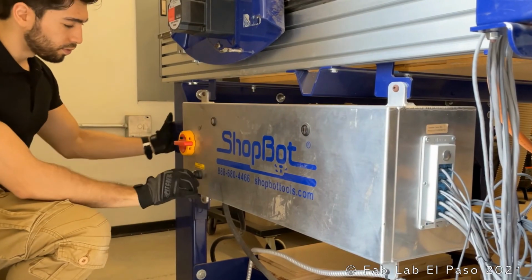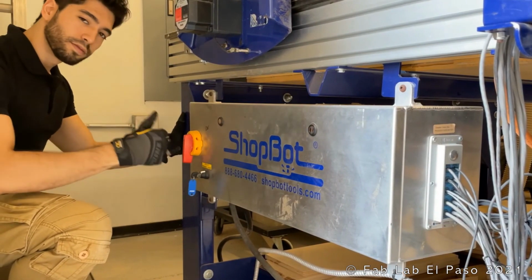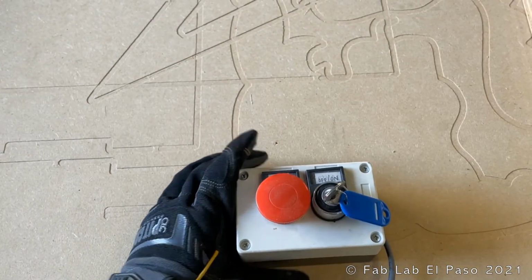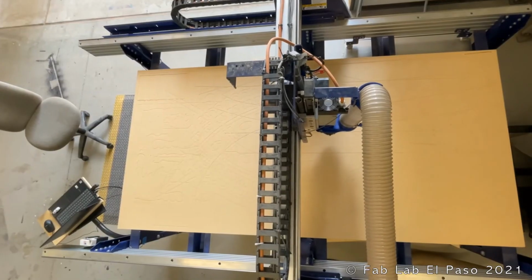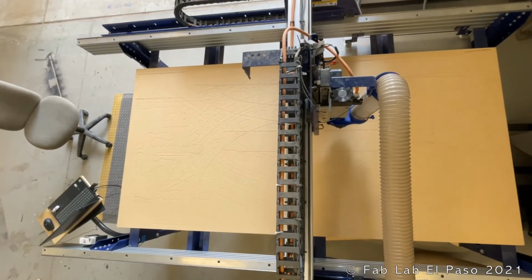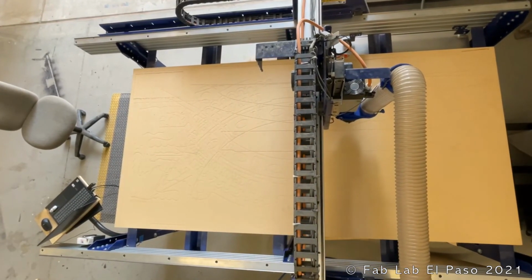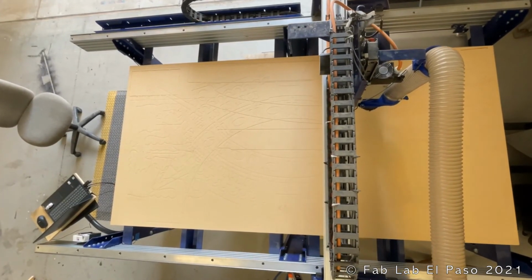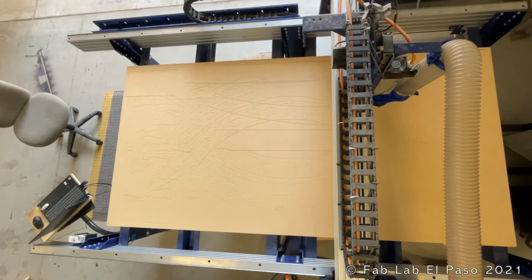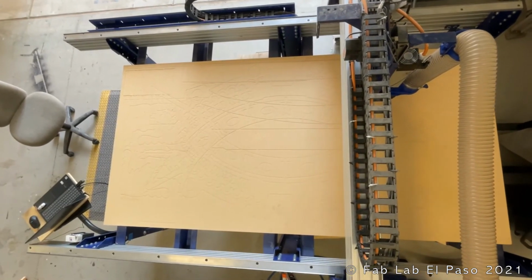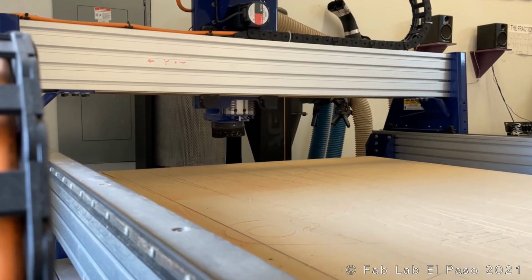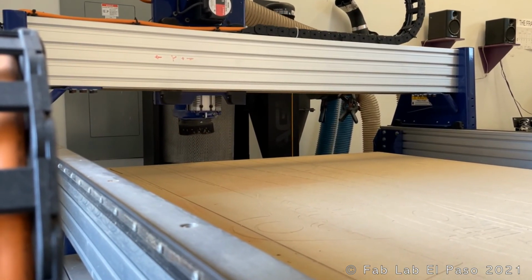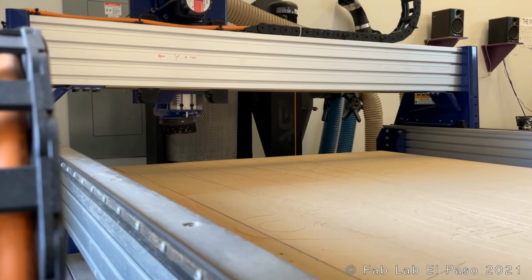Now, here at the workshop, I'll turn on the CNC, make sure that the safe box is on, and that everything is good. In the computer that controls the CNC, I'll run the home routine for X and Y, where the CNC moves till it hits the proximity switches, and I'll know that my tool will be located in this corner. I can either locate the material there, or if I want to locate it somewhere else, I'll manually home it there later.